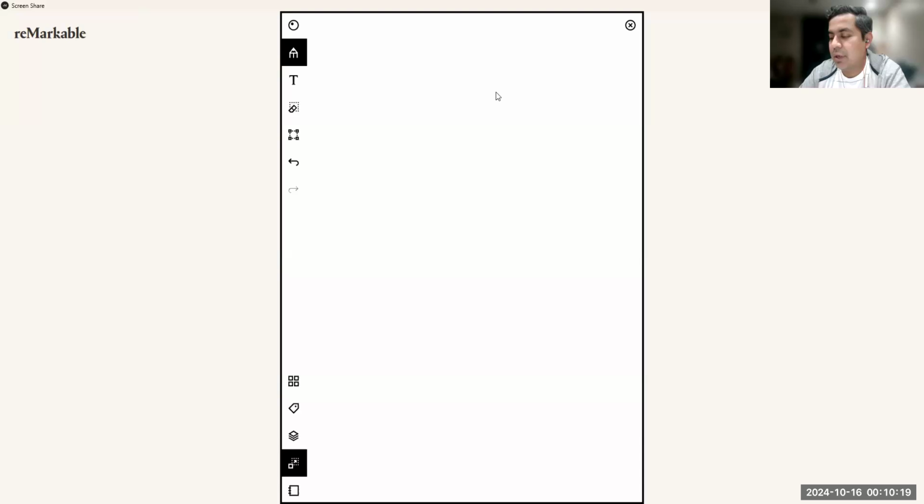And then after you run the simulation, you can calculate the lambda, Kn prime, and gamma values from those plots also. That is not mandatory. We are mostly focusing on determining the experimental value of these parameters, but you can do an initial check with those simulation values, whether they match the model parameters that are described in your model file for these constant device parameters.